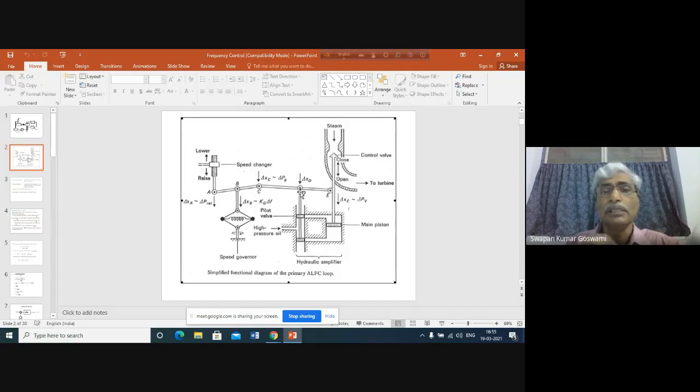As a result, D will be moving down, so reducing the previous opening somewhat here at this connection of the two chambers to the cylinder of the hydraulic amplifier. So in this way, the system will behave following a command of power increase. Okay, so this is how the system will work.